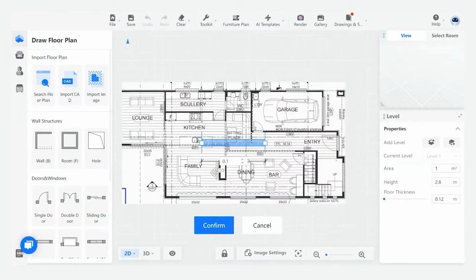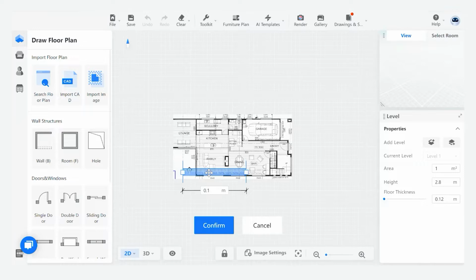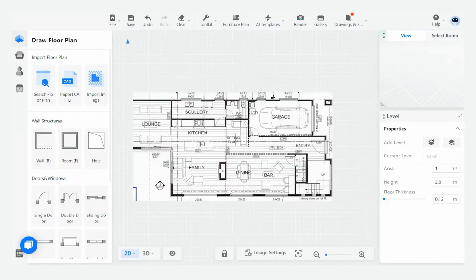Then it's time to set your scale, because the image of the JPEG file might not be so accurate. So now we can set a measurement that is correct and precise, as what you have here. Okay, so as far as I know, the dimension between these 2 axes is 18 meters, so I can put it here. There is some clipping on my image, but it doesn't matter.